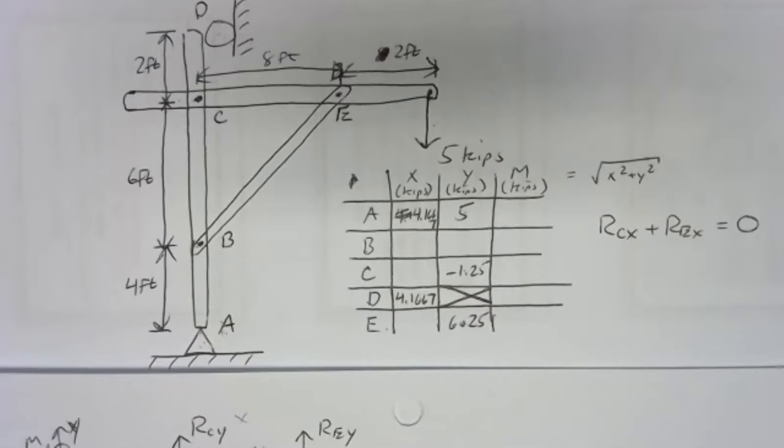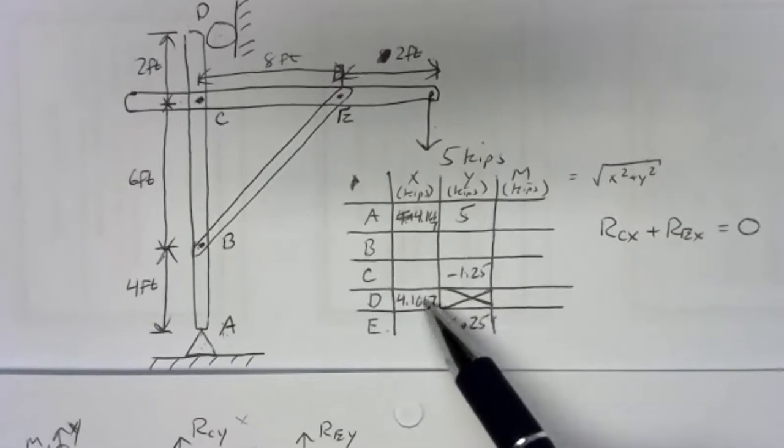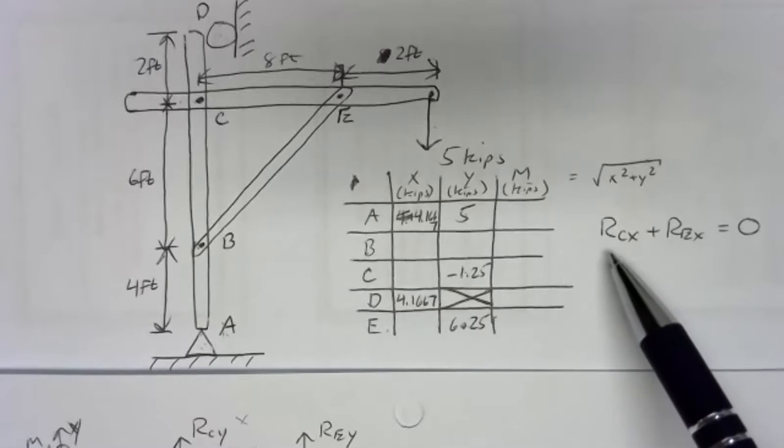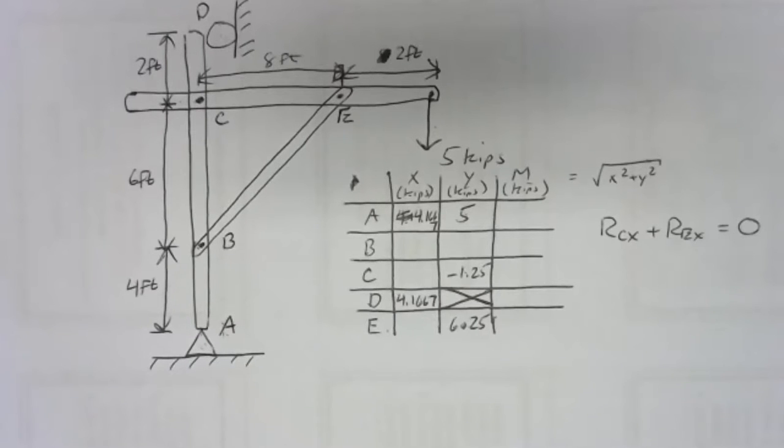And now we've got, out of our 9 unknowns, 1, 2, 3, 4, 5 of them plus 1 equation. So it's really 6 pieces of information, which is exactly what we'd expect after doing 2 free body diagrams at 3 equations apiece. But that's all I can get out of the horizontal member. So next we'll do the vertical member.